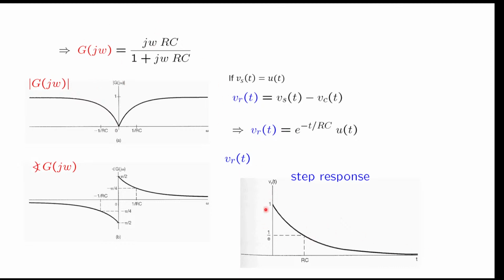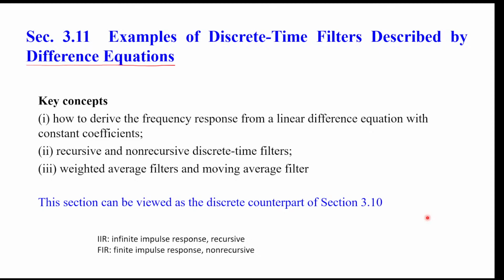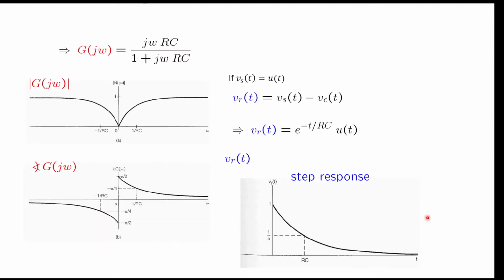Then we'll look at this, and once again you see that you want the sharper filtering out, so you want the smaller 1 over RC, then you want the RC larger, and you will get a larger response time. Okay, and so that's a filter for continuous time.